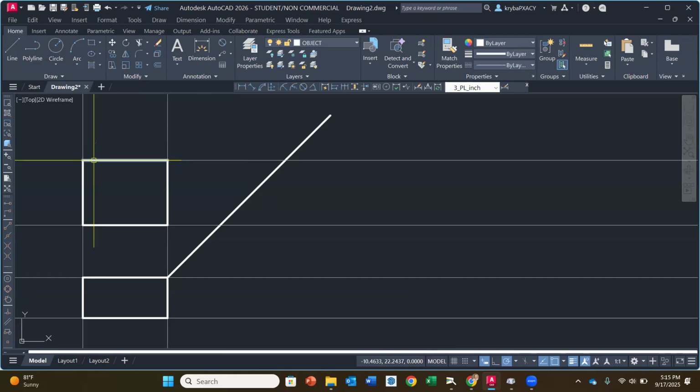Now, I'm going to use the miter line to create my right side view, because with that miter line, it's going to set the distance away from the front view. You can't just start drawing a front view over here if you're going to use that miter line later on. So we need to use the perimeter. So the two horizontal lines for the depth dimensions in that top view, we're now going to bring down to create the width of our right side view.